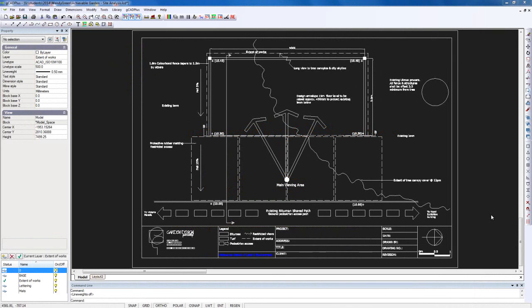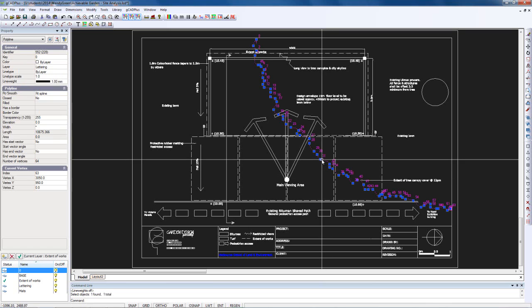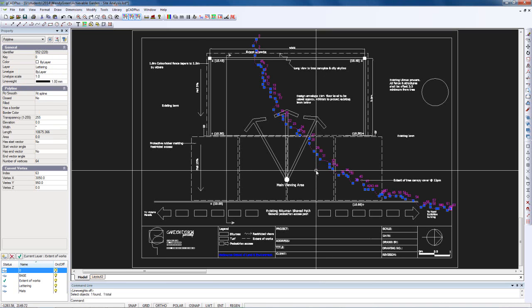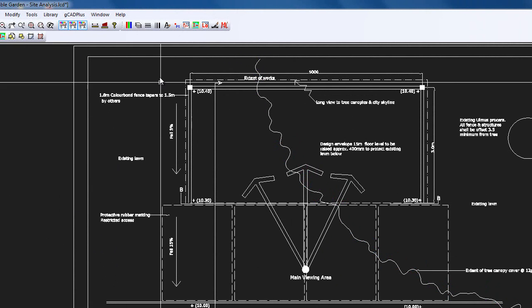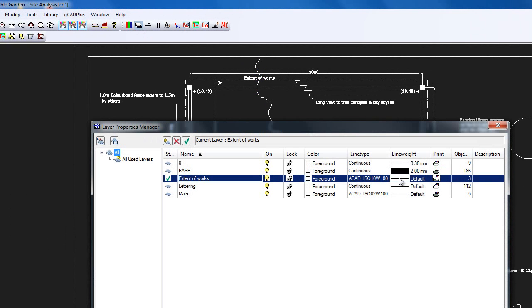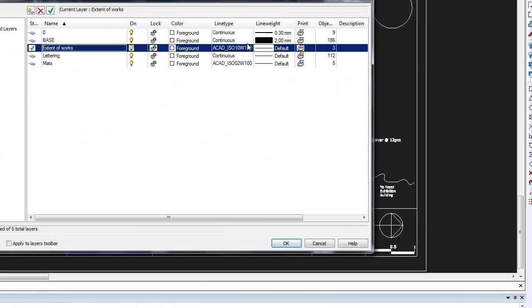The designer of this space is having difficulty controlling line weights. The reason difficulty is being experienced is that there's been a muddle of assigning line weights. Some entities in the drawing have their line weights associated directly by setting a line weight value, in this case 1 millimeter, and other entities are being placed on layers, and the layers have line weights associated with them. So there's quite a muddle.